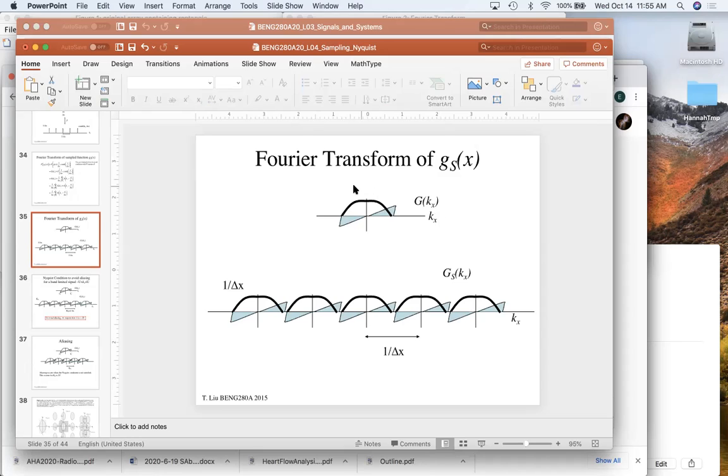All this slide is saying is that if this is my actual spatial frequency content in my picture, when I sample that picture at a gap of delta x, and I represent that object with these discrete values separated by delta x, then I will see my underlying true bandwidth of the signal in addition to these other sidebands.